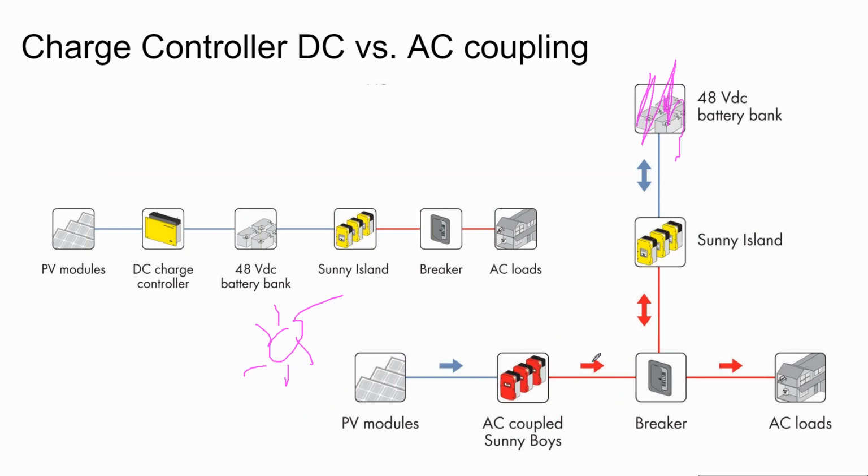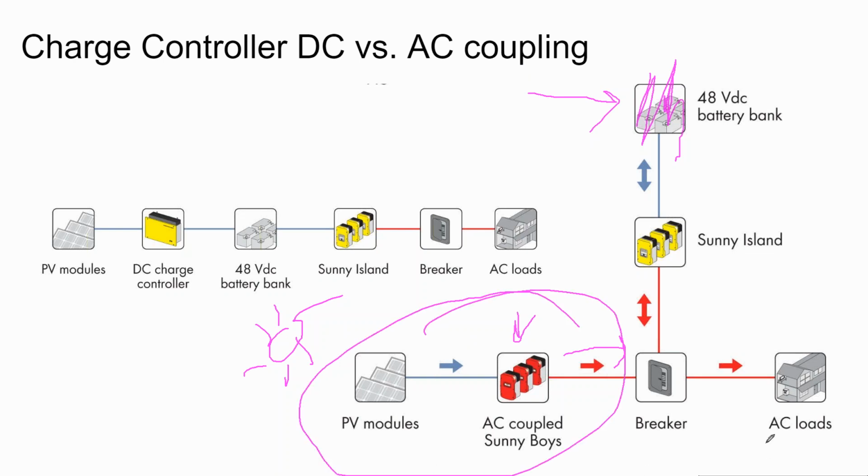Well, you have to remember in AC coupling, these are inverters, and commonly they are grid-tied UL-listed inverters, which means they have to see a signal from the grid in order to turn on. And so if your battery bank is fully depleted and the sun comes back up and you're fully off grid, your solar array will not turn on because it doesn't see any signal.